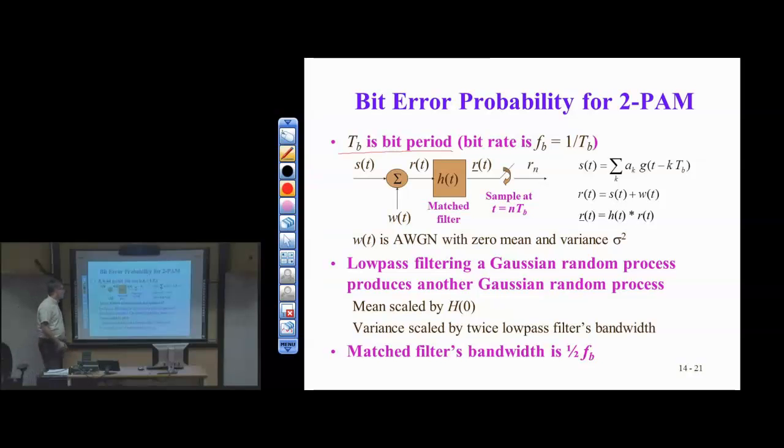The operations here are very similar to what we had before. Again, I have a transmitted signal, which will be my pulse-shaped transmission of PAM, and that's shown over here on the right. Just interpolation. AK here is the symbol. AK are the symbol amplitudes.